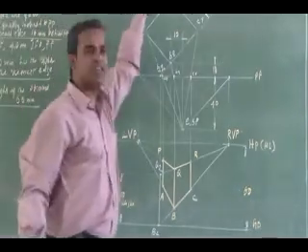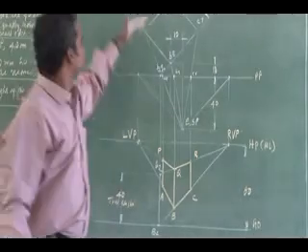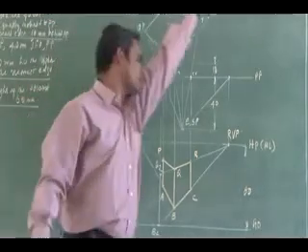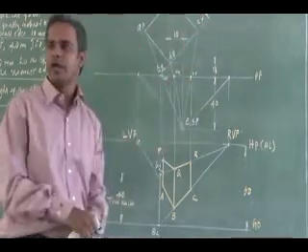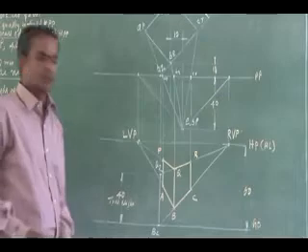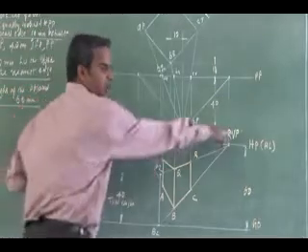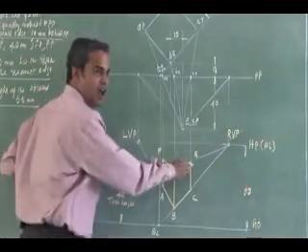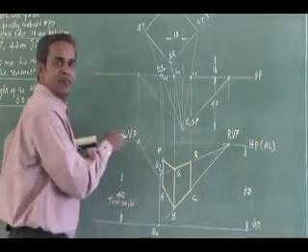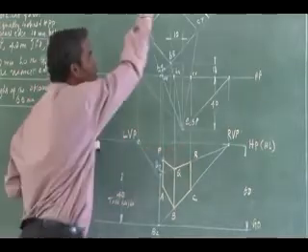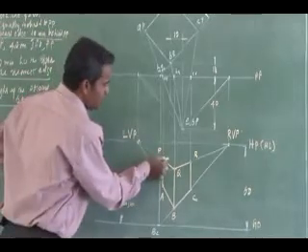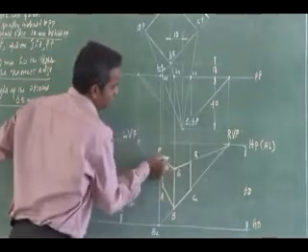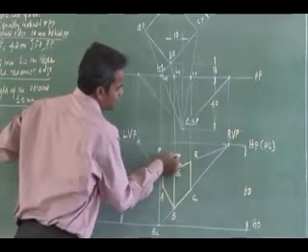What about the other corner DS? How can I obtain it? So this face is going to vanish to the right side. This face is going to the left side. What can I do? Easily. This corner P, I can join it to the right vanishing point. This corner R, I can join it to the left vanishing point. Wherever it intersects, that is going to be my PQRS. So this P, I can join it to the right vanishing point.